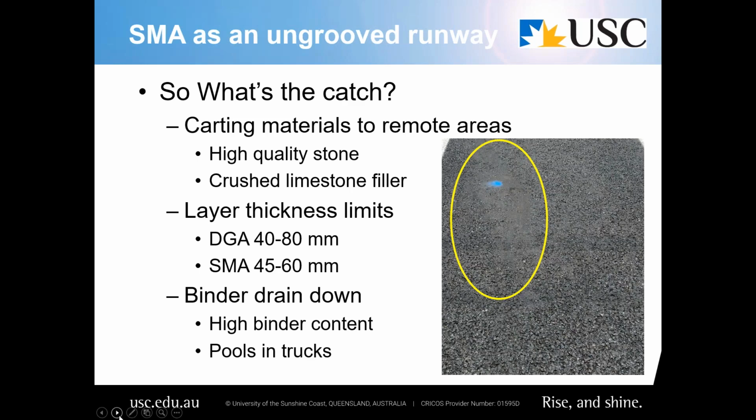But in total, that has affected about 3 square meters of the 80,000 square meter runway at Emerald, and they've just been left in place. They haven't been treated. If you do a sand patch test on them, the texture isn't as high as it should be. But 3 square meters out of 80,000 square meters isn't something anybody's losing any sleep about, not at this point in time anyway. It's just something that needs to be managed. Incidentally, at Emerald, once this became apparent, the contractor changed their processes. Boral was quite proactive. They changed how they were loading the trucks up at the start of the night, and generally we didn't see that happening anymore after those first couple of shifts.